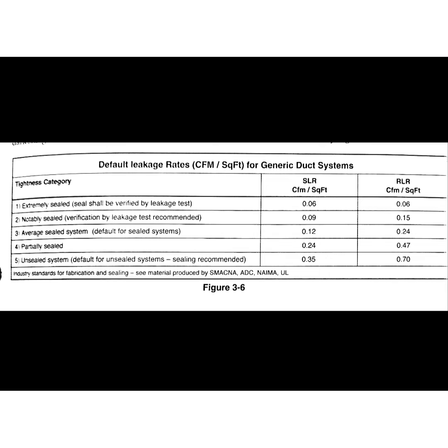But it's pretty safe to say that on a really cold night, the blower is going to run pretty much continuously all night long. So for that night, we're going to be pulling in all that dry air with absolutely no break. And our humidifier needs to be sized to be able to maintain humidity in that scenario.